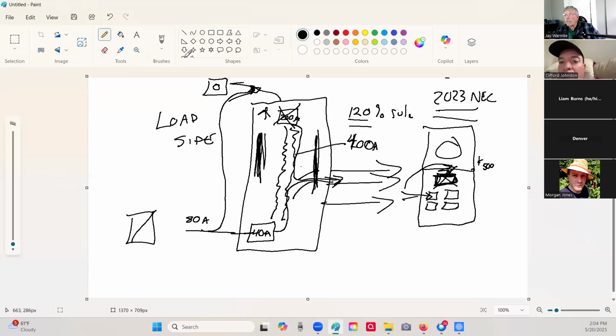I've got bare copper ground wires going in there. And the reason is because we bond these two together so the neutral and the ground are effectively the same thing. You're grounding your neutral wire. It's referred to as the grounded conductor. Okay. You can only do that in your main box, in the box where the main is.